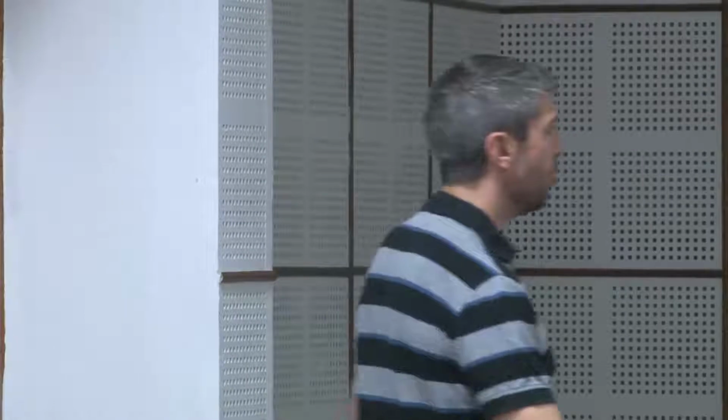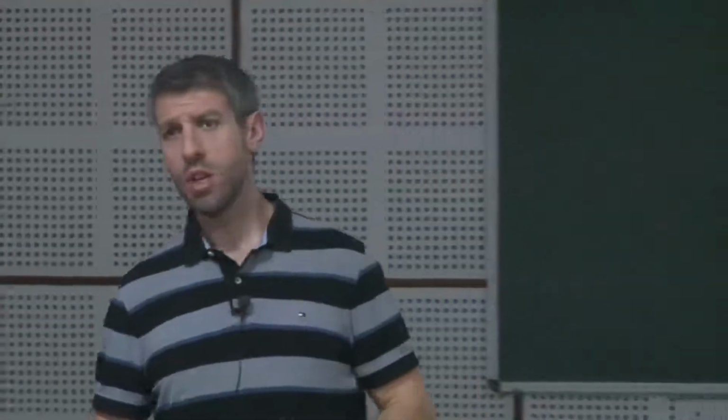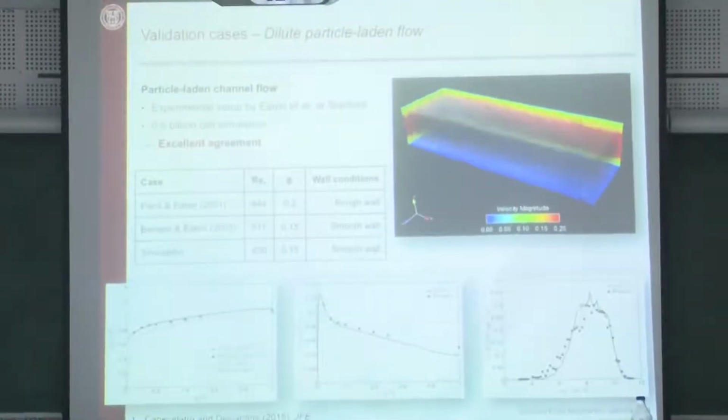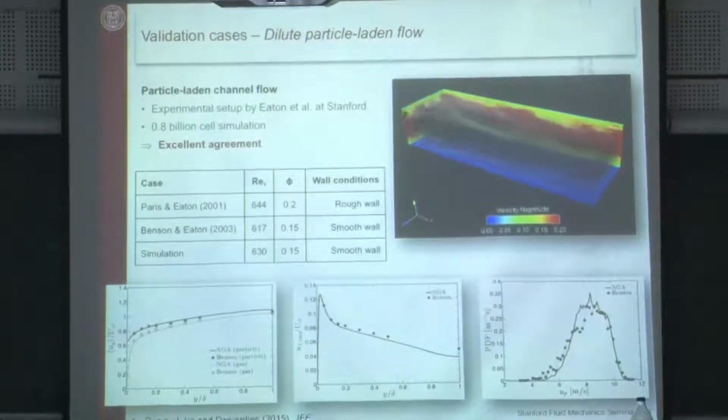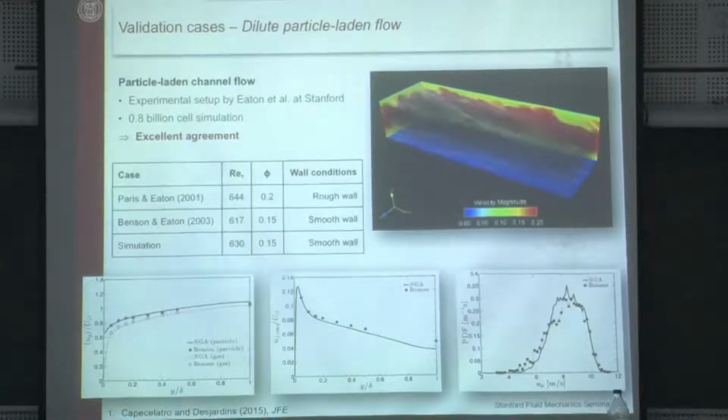So provided you kept the Reynolds number the same, you could change this height, nothing would really change. If you were in a situation, however, where the mass loading was sufficiently higher, then the particle dynamics would essentially control the entire flow. And then you would end up with a very different story, because this is where you would transition to clustering.